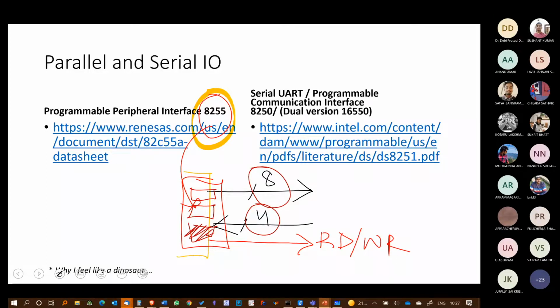You can also say, give me another wire for read or write, which I can set to 1 or 0. Once you've programmed it, the 8255 will give you these ports. You can now write to that port, read from that port, and raise that read/write pin high. So if you have ever wondered how to bring these pins out if the 8085 itself does not have them, the answer is to use an 8255 and get those pins for yourself.